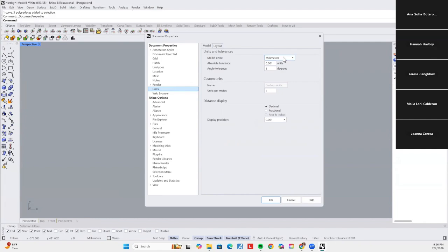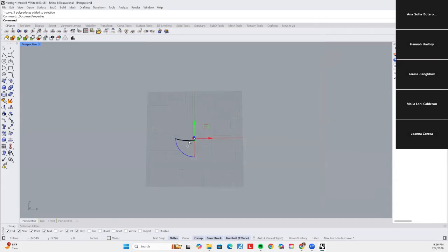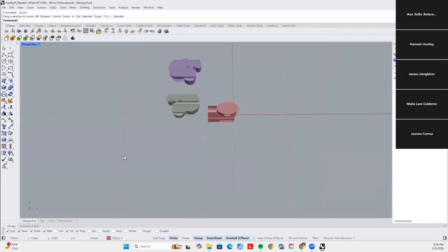So she already had it in millimeters, but basically if I were to go backwards, because some people have never done it, you go inch, you would go millimeters, and then you have to make sure you say change unit system and maintain object size. That's what's important because then it changes everything, and that's when you would do length and it's 9 inches.